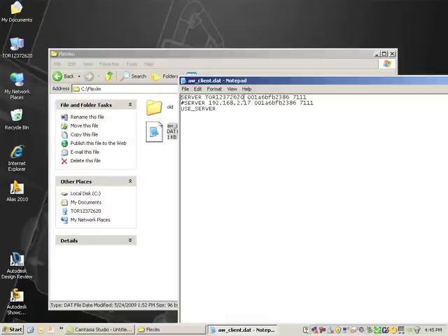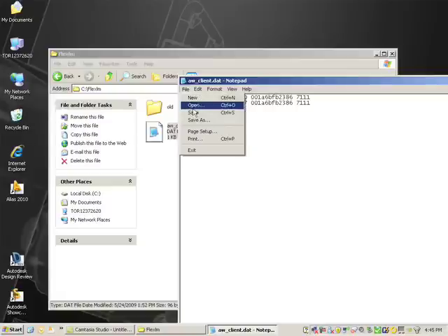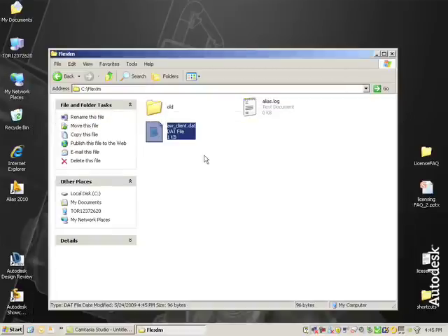Another thing I would try is to change the IP address. So again, you would have to update the server license file as well. So what I would do is on the server and the client, I would comment out the line using the host ID. Oops. And I would save the file, and I would do the same thing on the server side.